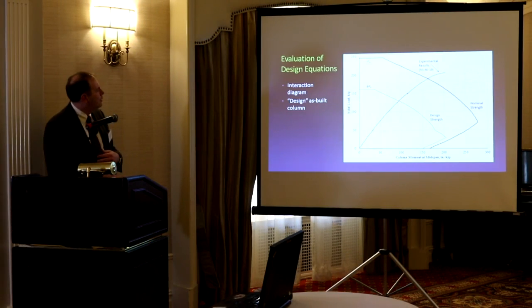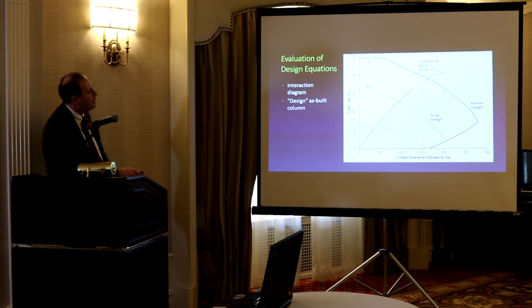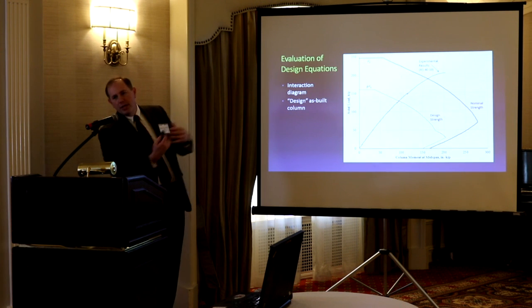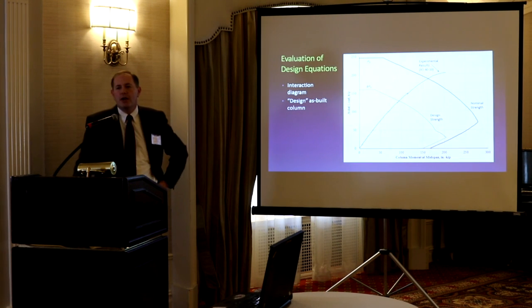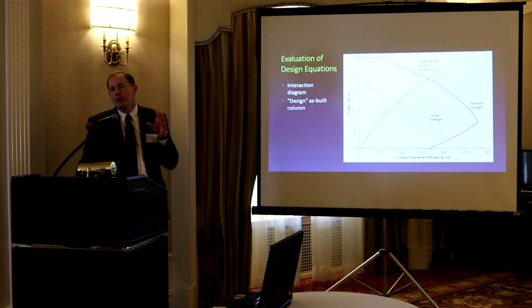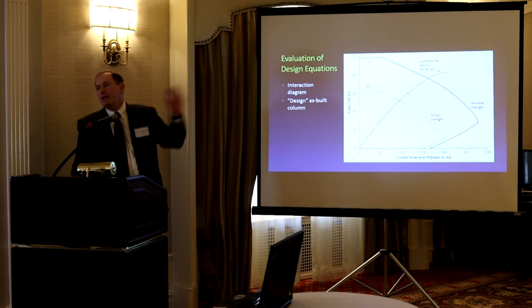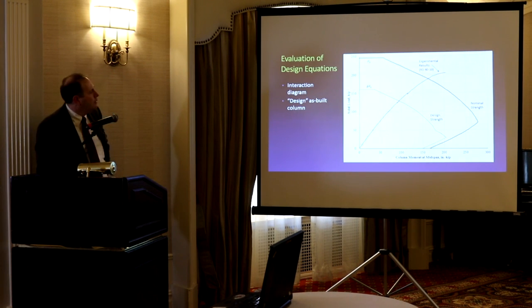deflection. So let's just look at the design equations I just mentioned before. This is the nominal strength curve. This is the design strength. So this is where ACI would bring us in with our phi factors for the safety. Experimental results, we're looking good. I mean, in all cases, our tests fail beyond what ACI would allow you for design past nominal. Okay.